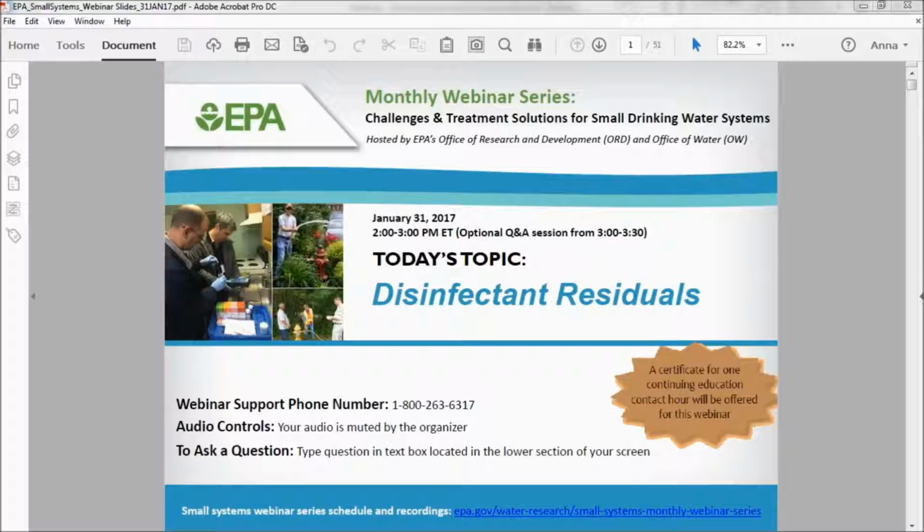Okay, yeah, that's good. That answered a couple other questions. Also, here's one, and I'm blending a couple questions together here: in systems that have higher chlorine residuals yet come up E. coli or total coliform positive, can you talk about the ratio between hypochlorous acid and hypochlorite ion and how that might impact the results? Maybe throw that to Dave.